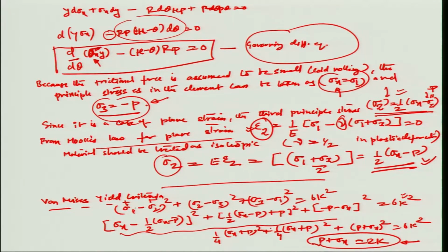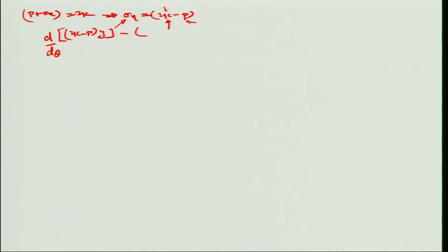So we have a plus minus mu term incorporated here, and we can write this as minus plus minus mu minus theta rp equal to 0. If it is aiding the process before the neutral point, the sign of the friction coefficient is positive, and we assume that the friction coefficient is disabling the rolling process, acting in the direction that prevents rolling from happening, after the neutral point. That is why minus mu. Please understand this very carefully.